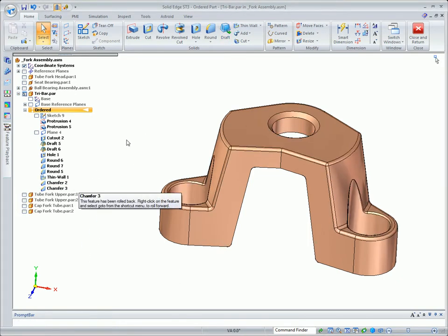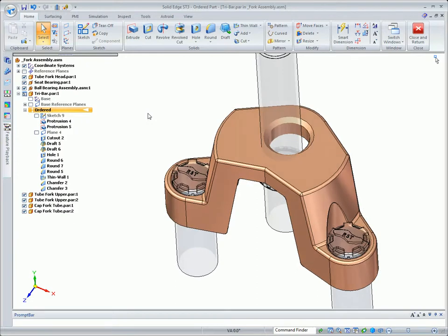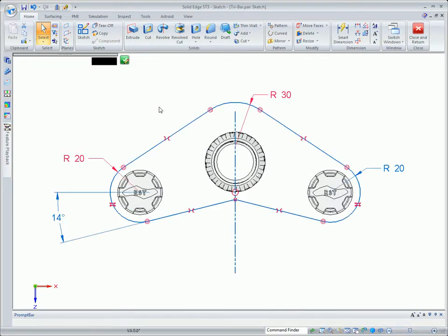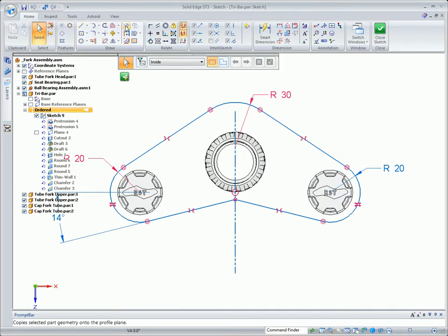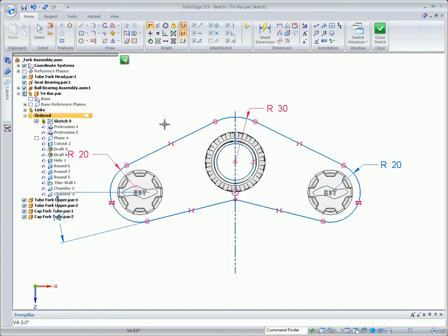According to our markup, the next thing that we need to do is make sure that our center hole aligns with the shaft. We also want to move the stanchions out 35 millimeters. In order to do that, we have to again roll the model back in time so you don't see the edits in real time or the impact on downstream features. All the dimensions are contained in the sketch. Because we use the feature playback to help interrogate the design, we're able to narrow down where the feature is that controls the edits that we require.